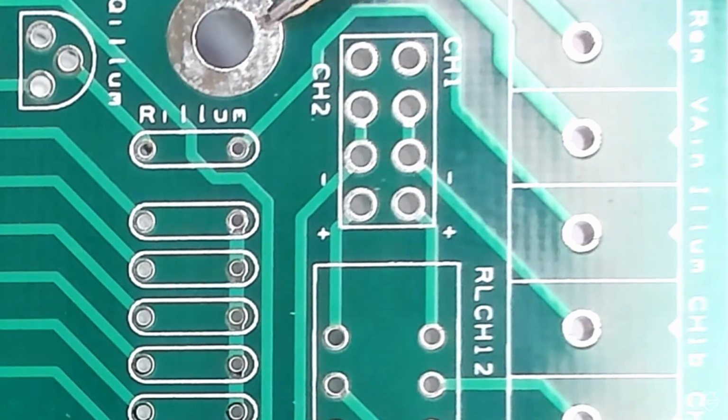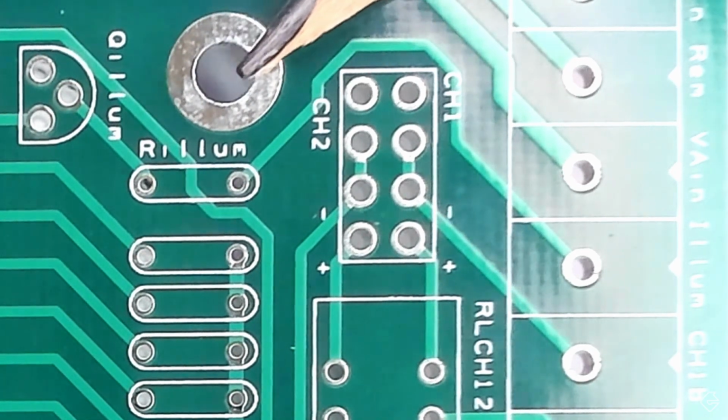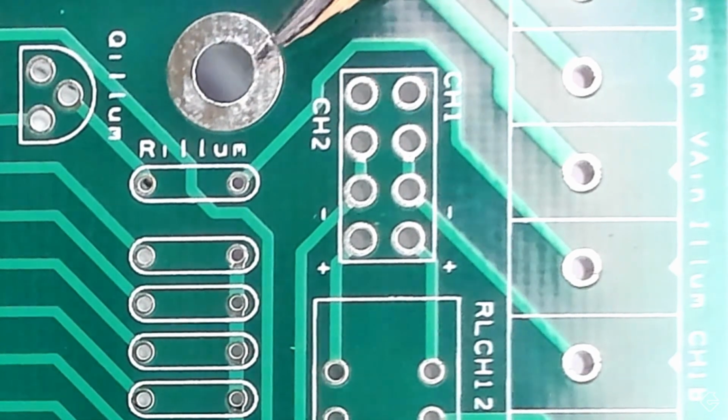The exception, though, and it might be glaring here, is some of these really, really giant ones, like this one over here. And the reason is I made this giant hole not for an electrical component. This is actually for a screw. So this is the anchoring hole that we need to use to anchor that PCB to something solid, the actual case. So in that situation, I don't follow that rule. Because there's no electrical connectivity, I'm basically just making sure that the annular ring is big enough to cover the actual screw head. So that's a totally different thing. But for most electrical components, 0.7 is what I do.